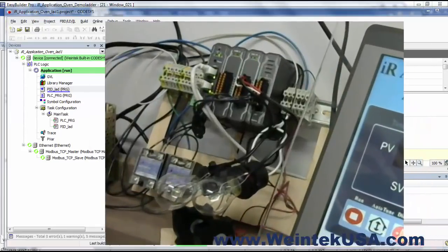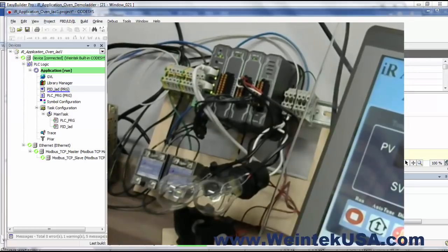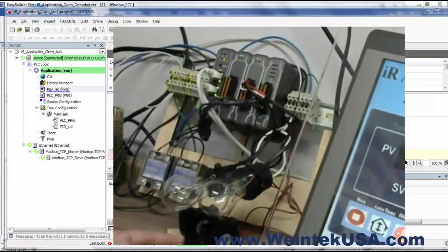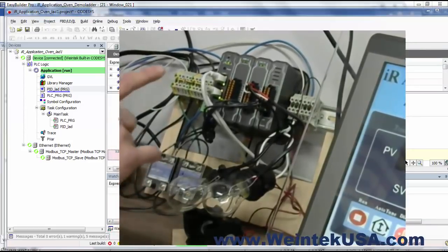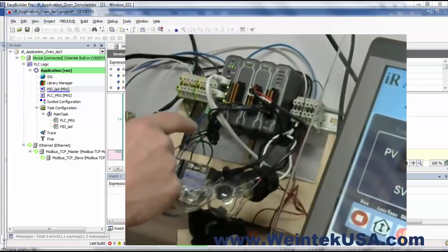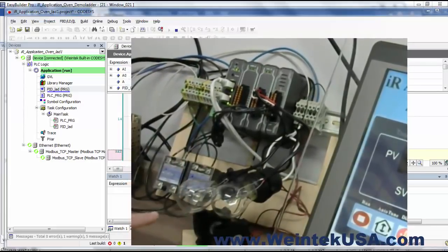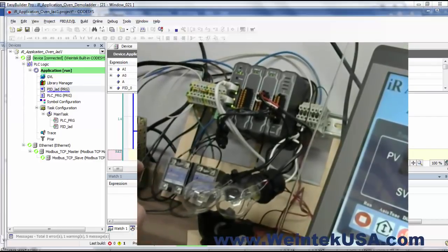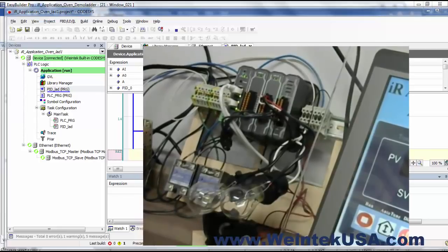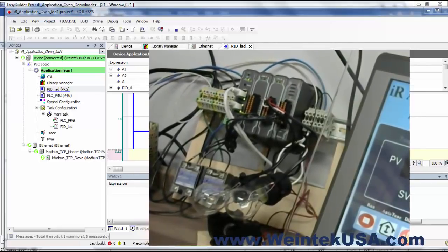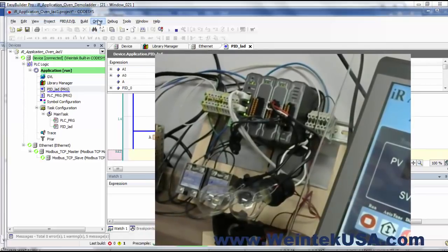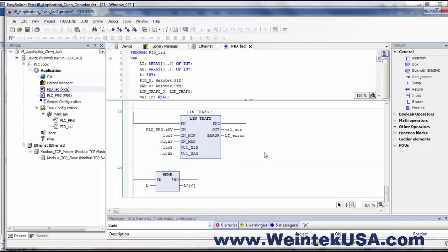I decided to go ahead and make a little hardware change. You can see here now I've added a little blower, to simulate some thermal mass on our application. These are actually 12-volt fans, and I just wanted to hook them up to a digital output. And so I've actually got them linked together so we won't overvolt the fans. But I do want to set up a little pulse output for that. So we'll go ahead and write that code together if you want.